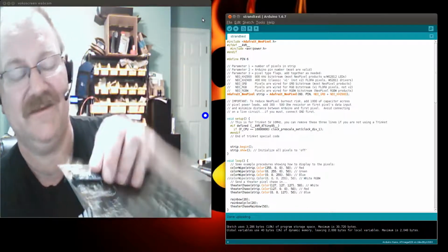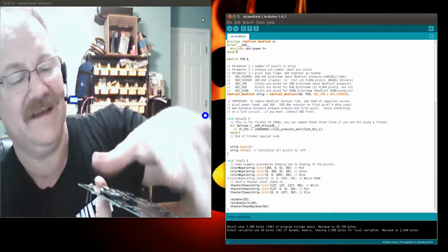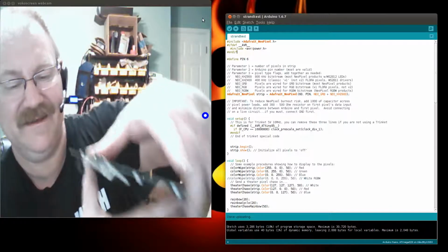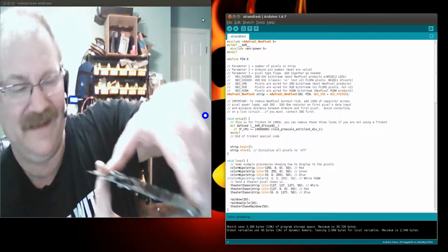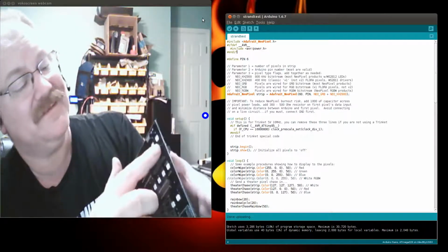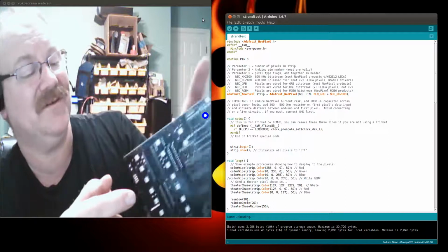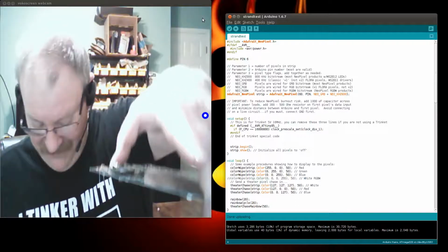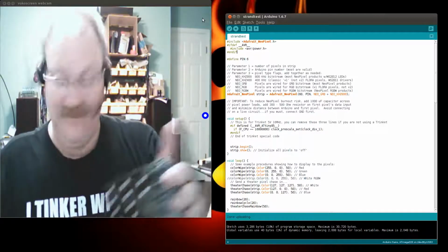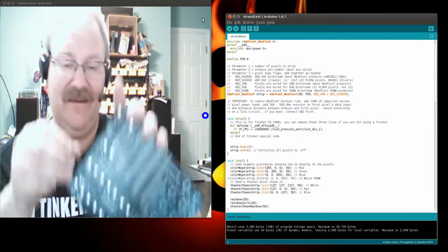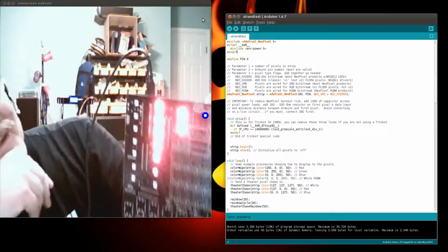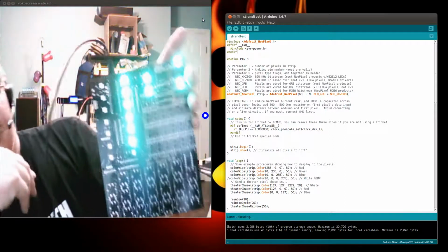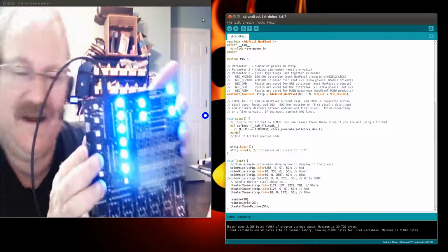Then I'm going to show you a little trick for testing. You put your thumb on the side of the Arduino Nano, and you'll see that it will rock in the pins but won't quite come out, because the pins are long enough that they wedge in those holes. We put our fingers on the other side of the board and just hold the Nano there. Then we plug the Nano into the USB. It'll power up, and ba-boom. Uh-oh. Not all of them light. Imagine that. So this board has a problem.